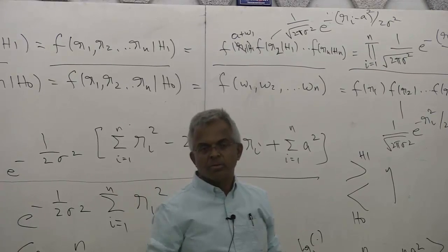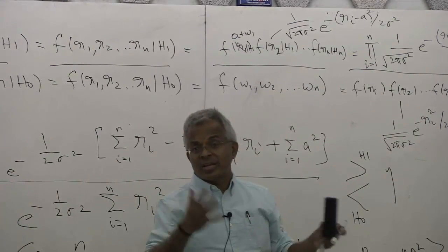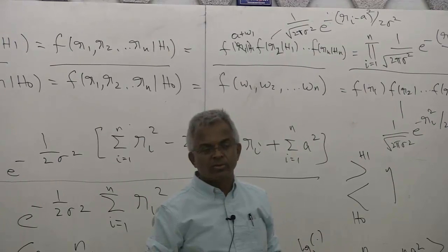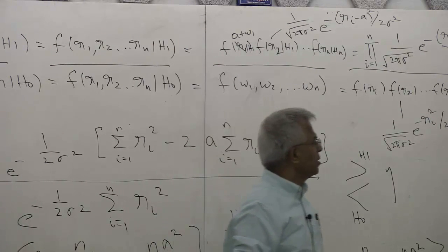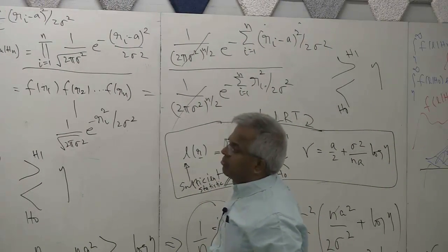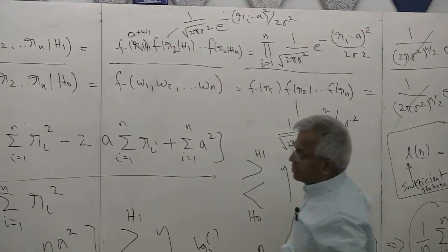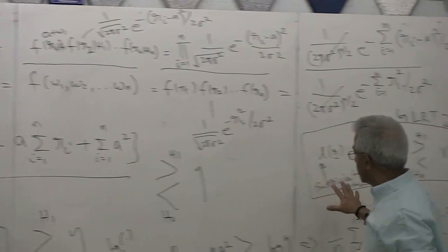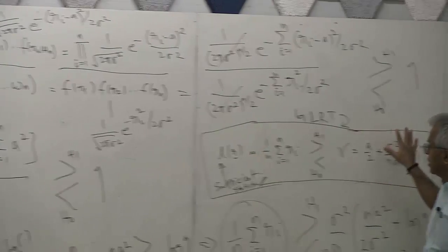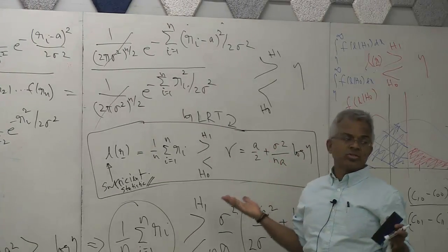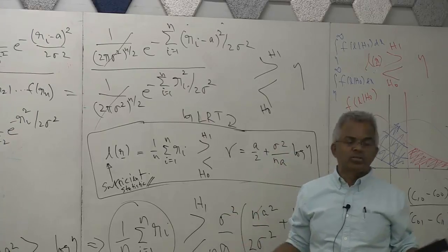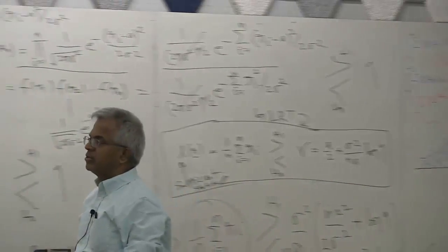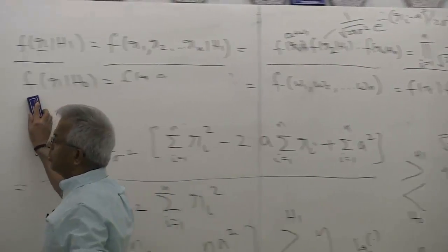So you are a champion of probability. Excellent applications of probability. Now you begin to see why what we did there makes independence, etc. Again, if you need to brush up, you need to brush up on probability. So we just found the best detector. The best detector is: form the average, compare it with the threshold. The next question is, what is the probability of detection? What is the probability of false alarm, etc., in this problem? So let's try to compute them.